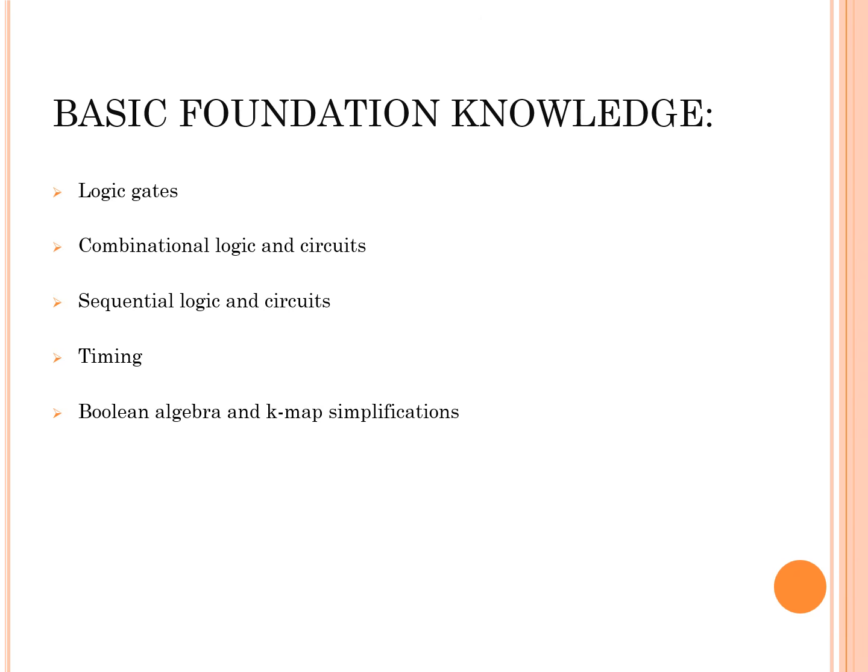Before we dive deeper into VLSI, let's first understand the basic foundation you need to get started. At the core, everything begins with logic gates like AND, OR, NOT, NAND, NOR, XOR, XNOR. These are the fundamental building blocks of digital circuits. Then comes combinational logic, where we design circuits like adders, subtractors, mux, demux, comparators, code converters, ALUs, and even 7-segment decoders, all working without any memory element.